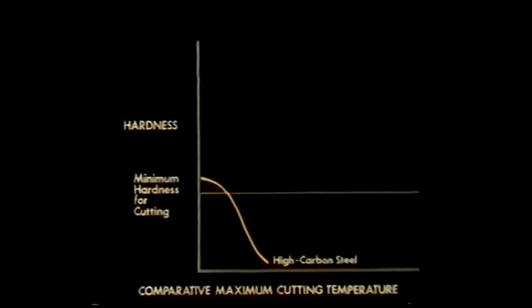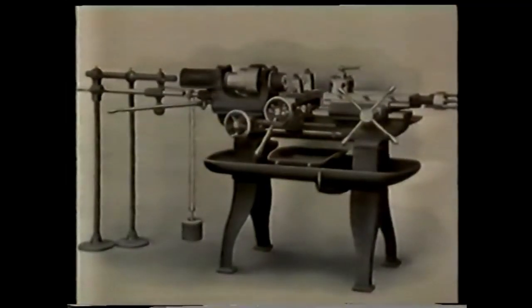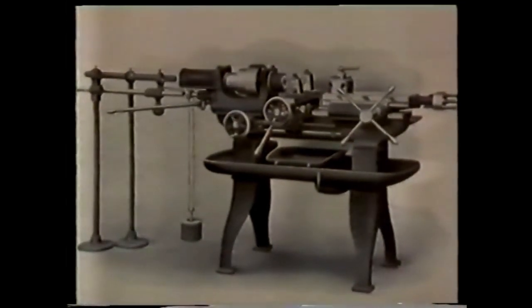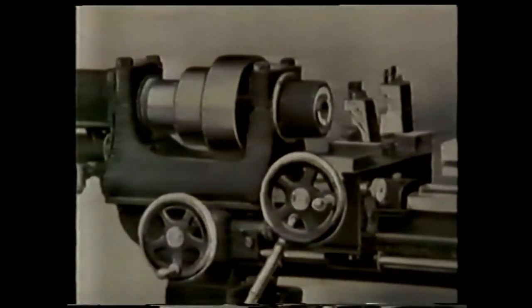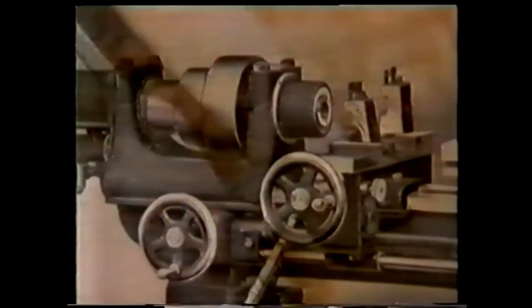of a nuisance. When you're using high-carbon steel, cutting speeds have to be kept relatively low. This was a severe handicap when high-carbon steel was in widespread use as a cutting tool for lathes like this one. Even the simplest cutting operation took an extremely long time. These days, high-carbon steel is mainly used to produce cheaper wood-cutting tools.